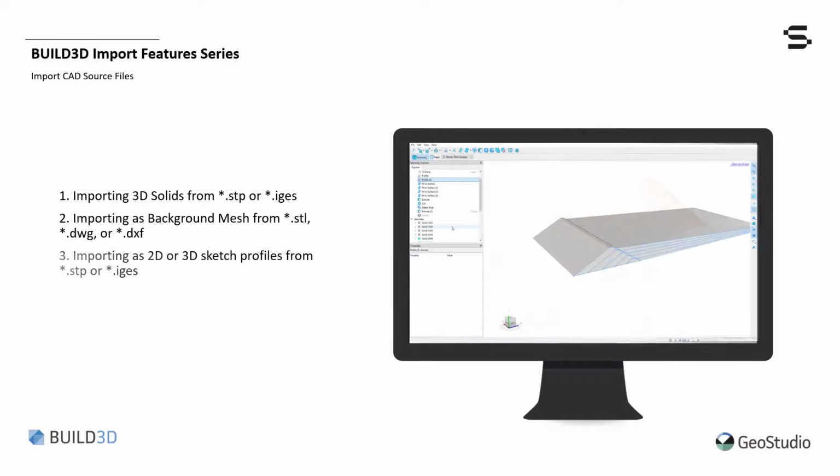The last option that I will cover today is importing as a 2D or 3D sketch profile. This third option for CAD importing is through 2D or 3D sketch profiles, which are useful for importing design structures, such as embankment cross-sections or tailings dam designs, into the three-dimensional geometry. File formats supported in this import type include STP and IGES format.